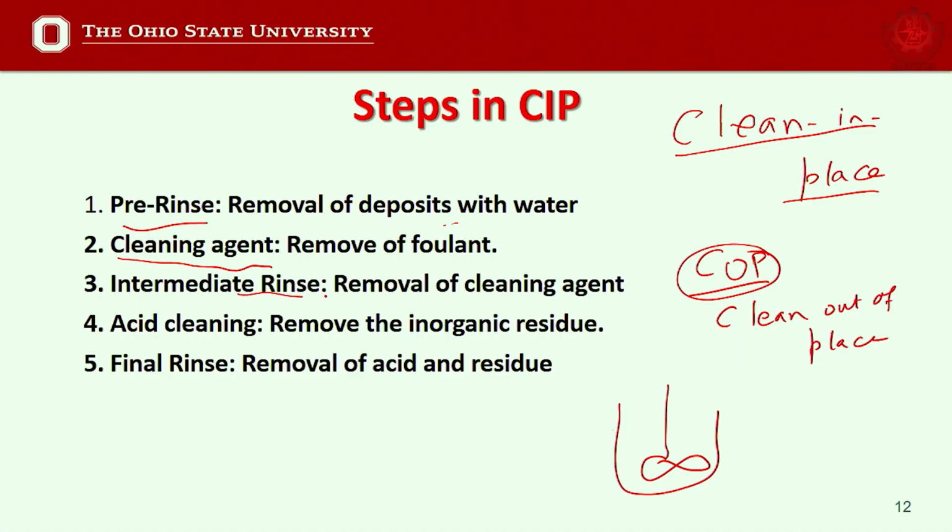So, you want to make sure you remove everything you can. The next step is, since you are passing through this detergent, there is going to be some detergent residue left within the equipment, and when you process your soup again next time, that becomes a contaminant. So, maybe you have to do another rinse, so that you can remove your cleaning agent.